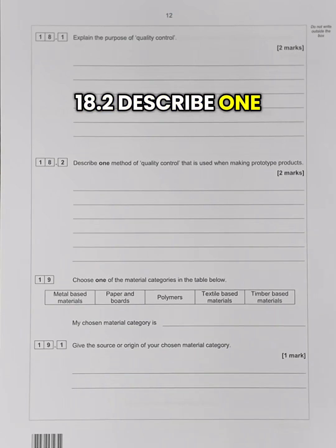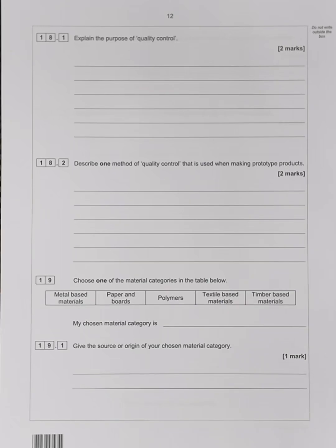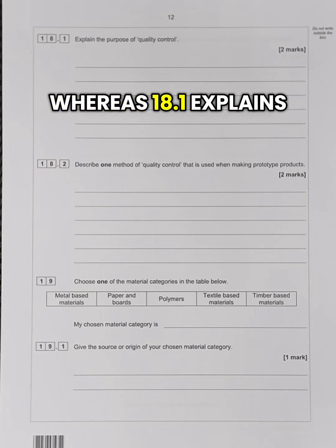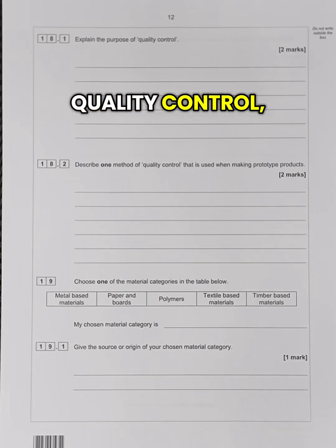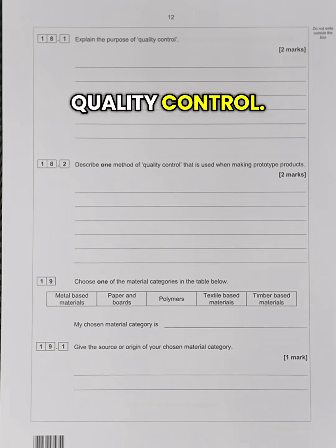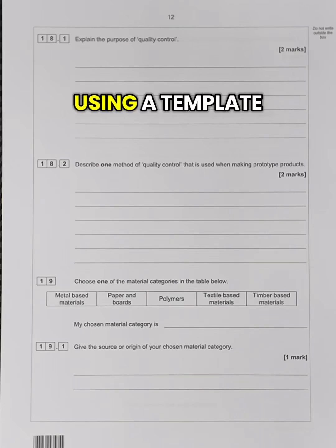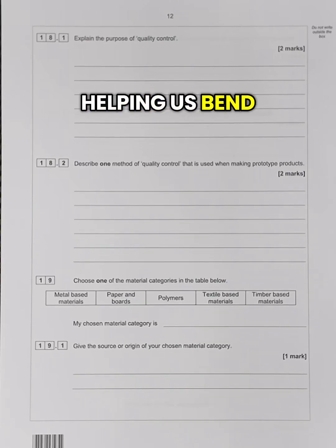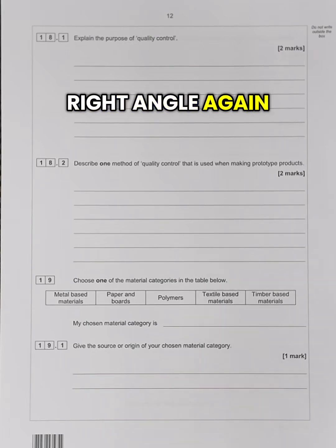18.2. Describe one method of quality control that is used when making a prototype product. This question is different from 18.1, whereas 18.1 explains the purpose of quality control, 18.2 you're asked a particular method used for quality control. So we can say using a template helps us mark out and make sure everything is exactly the same. You can say using a jig, helping us bend materials to the right angle again and again.